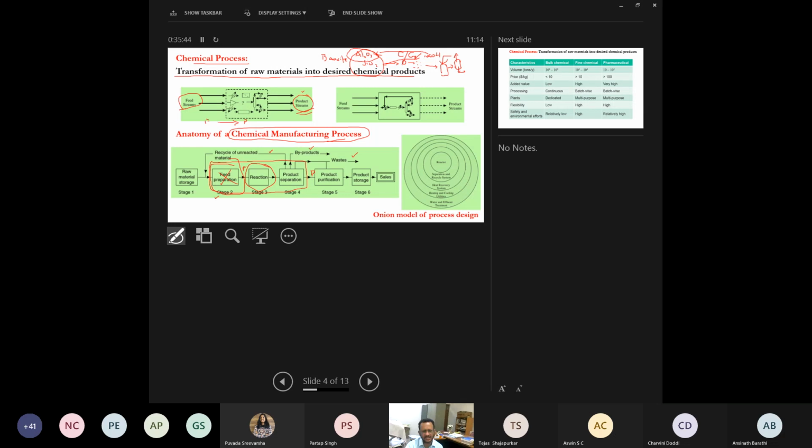Once the silicates are removed, it has to be sent to the thickeners, or you can say clarifiers, where we have Fe2O3. Normally this Fe2O3 will not react with this NaOH. So after removing the sodium silicate in the desilication tanks, it goes to the clarifiers where Fe2O3 is removed. So we have a series of product separations. Okay.